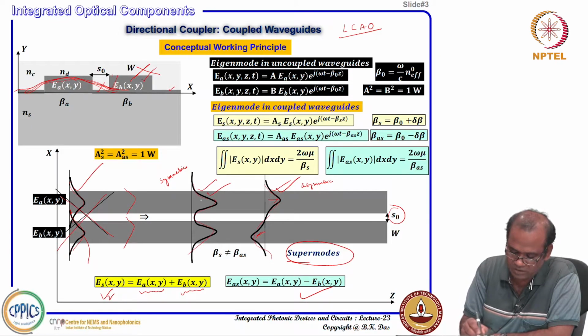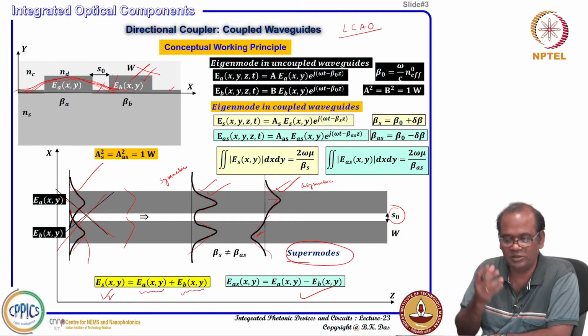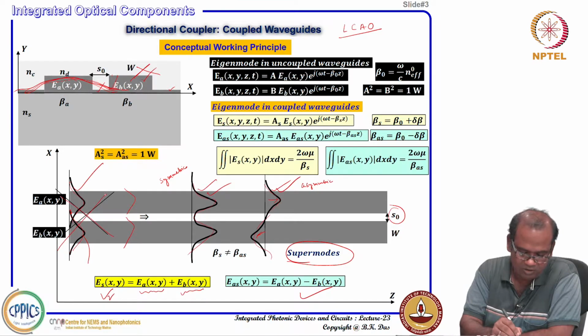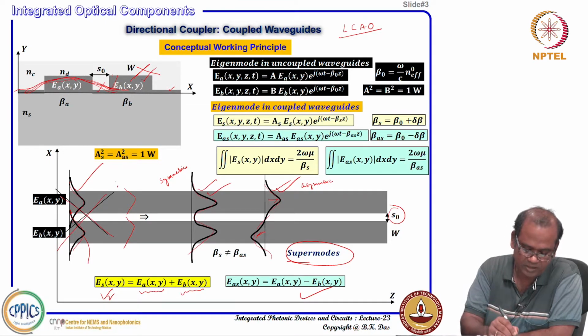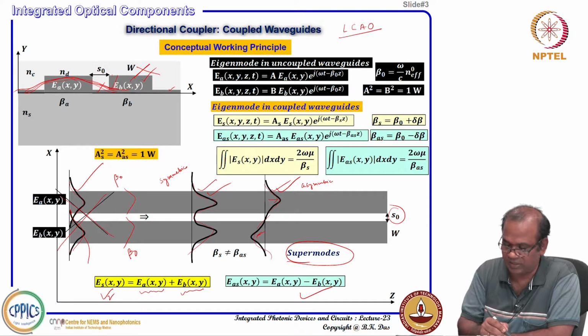And when they are split, what you would see is their propagation constant, that is the eigenvalue, right. The field distribution you get as a solution is the eigenvector, and the beta solution you get is the eigenvalue, right. So, originally, individually when they are separated you are getting beta naught, here also the solution was beta naught, but as they are interacting with each other you will be getting two different solutions.